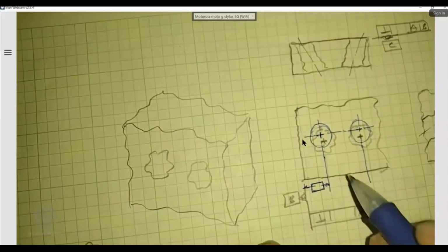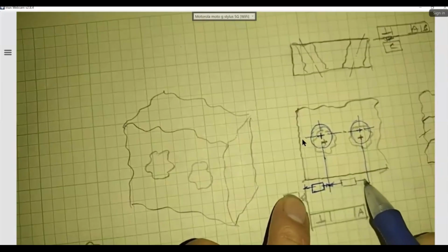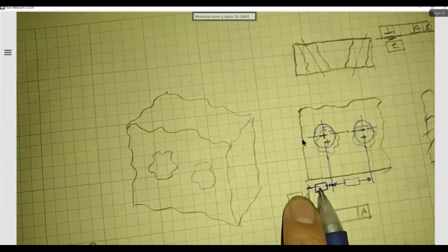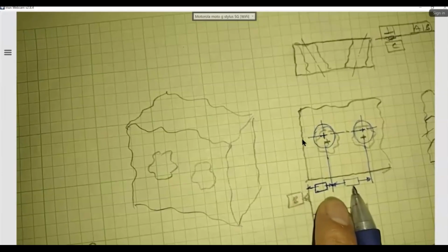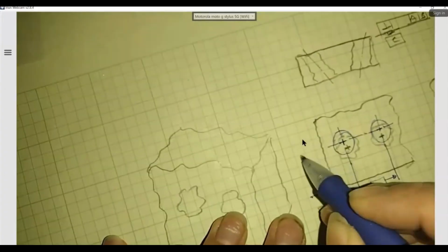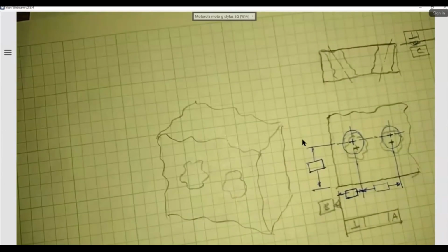Okay. And since this is perfect, I can literally go and forget about stack ups. You guys did stack ups not too long ago, right? Dimension and stack ups, plus and minus, and finding your upper and your lower limit, right? So I don't have to worry about it because this is perfect and that one's perfect. Okay. That one will allow me to know exactly where my bullseye is. Let's also go from the bottom datum and give it another perfect location on top. Now I know exactly where my bullseye is at.